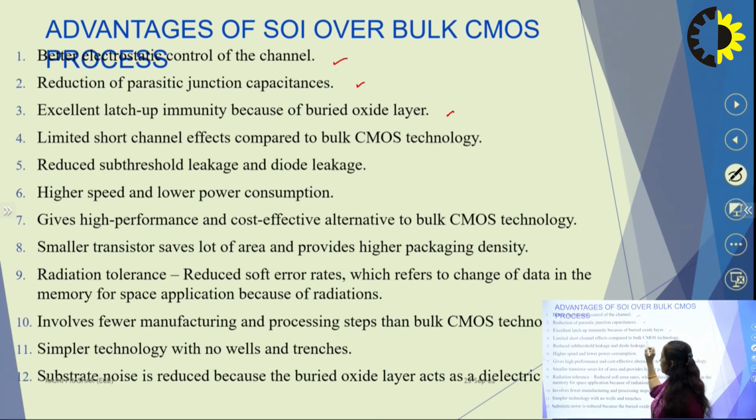Limited short channel effect as compared to bulk CMOS technology, and reduced subthreshold leakage current and diode leakage current. They can be used for higher speed and low power consumption. It gives high performance and cost effectiveness as compared to bulk CMOS technology. Smaller transistors save a lot of area, which provides high packing density, because no area is spent on the wells and trenches.